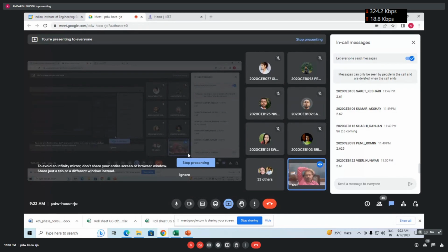So now if we see, you are in a position to design the pile. You have calculated geotechnical capacity, vertical load, lateral load, uplift, and moment. So now you can design the pile structurally.